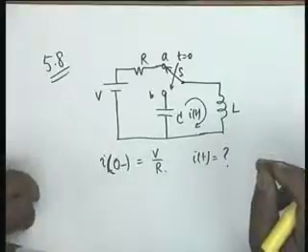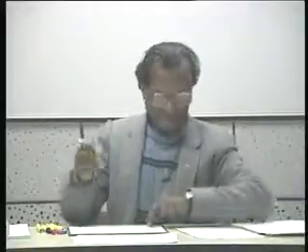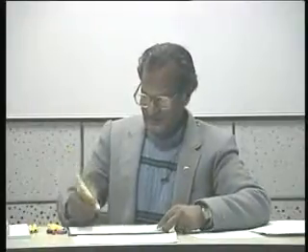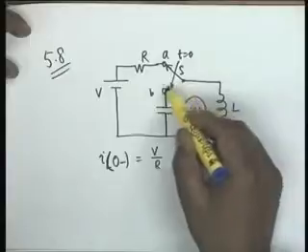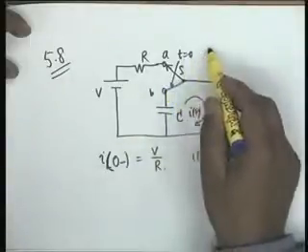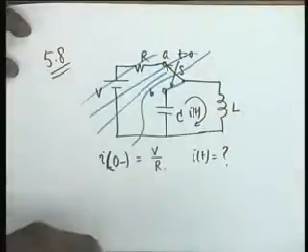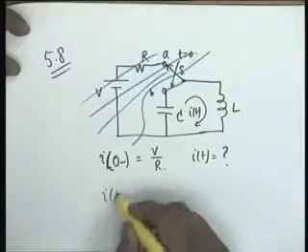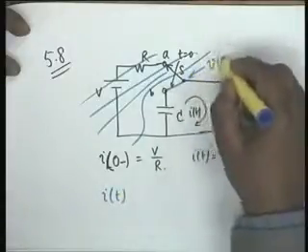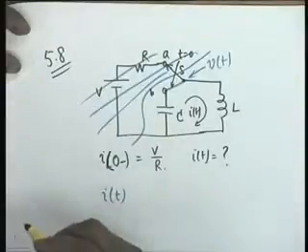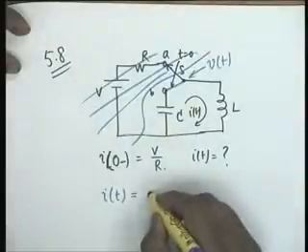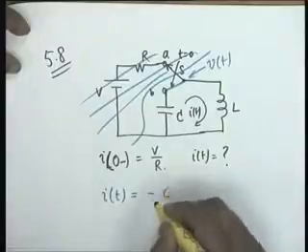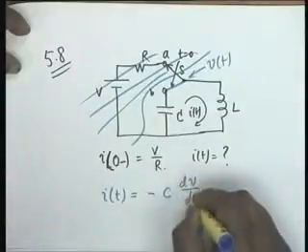Now let us look at it mathematically. Mathematically, the current, let me write it here because the circuit is here. The current I of t at t equal to 0 plus, the situation is that the switch has come here. So this part has become invalid at t equal to 0 plus, and I of t, if this voltage is V, then I of t is equal to minus C dV/dt. Do you understand the meaning of the negative sign?